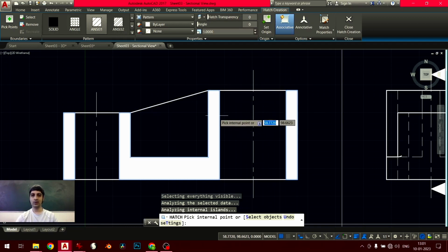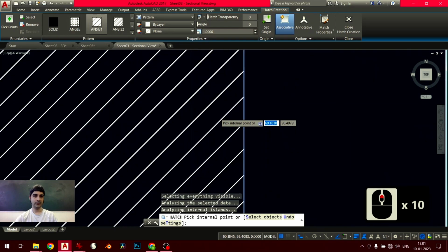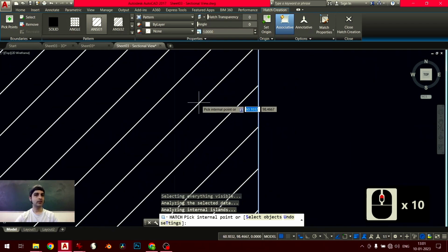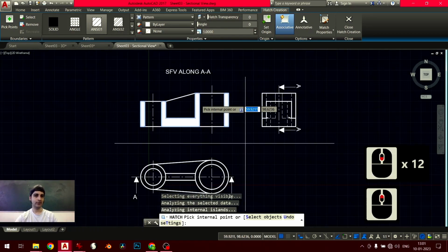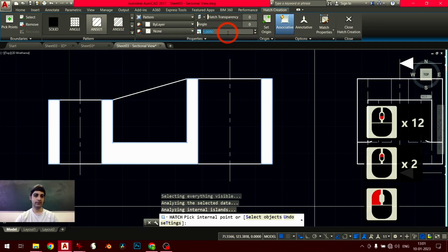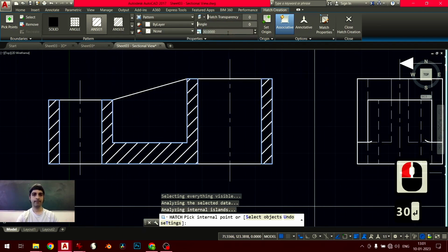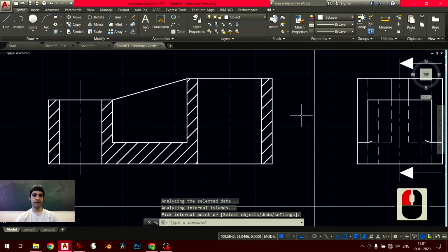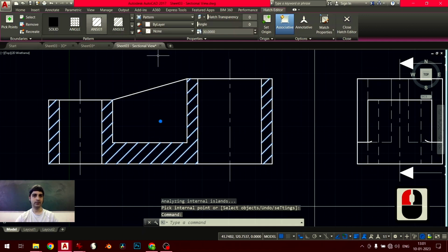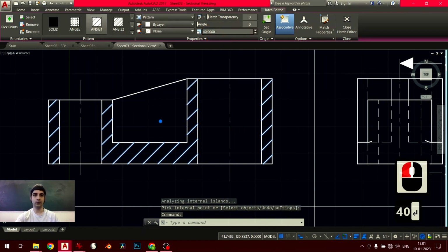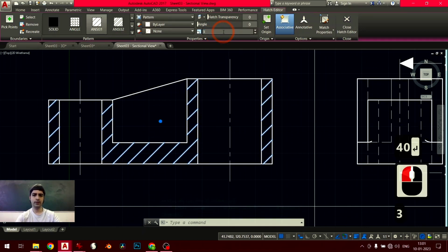You can notice that you can't really see anything. It looks like a big block of solid color, right? That's because there's a scale factor involved and the default value is pretty small. So let's increase it. We keep it around 30 or so. That's good enough. So once you're done, you can say close here. If for some reason you want to modify this, you can click back on it. Again, you get this box and you can play around with this parameter if you want. But 30 looks good enough for me.